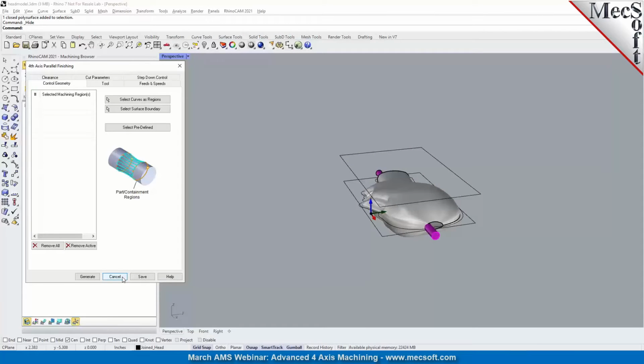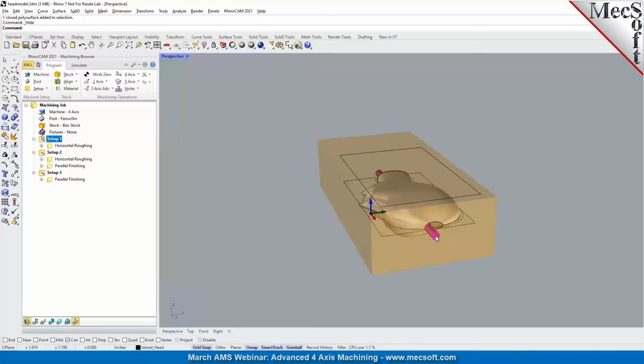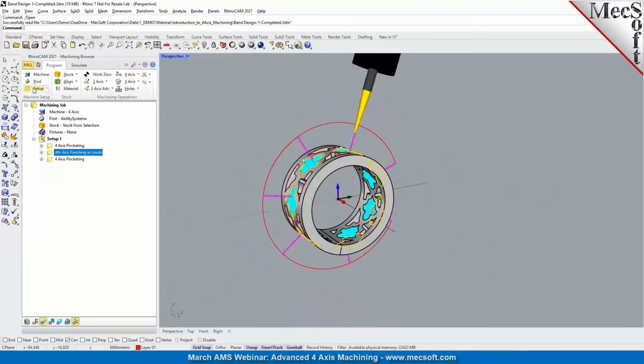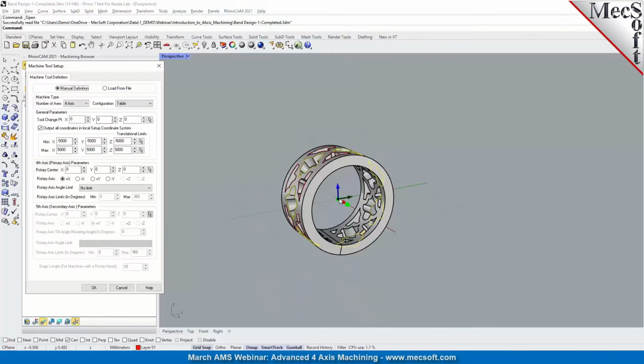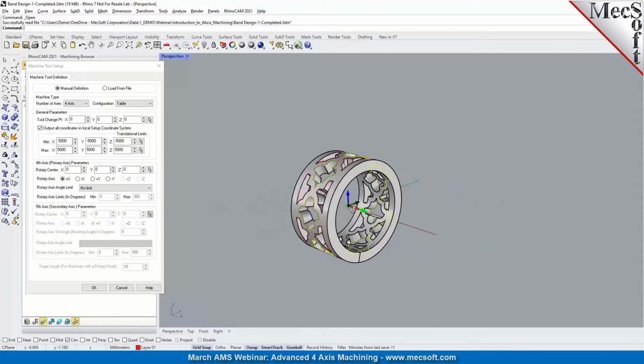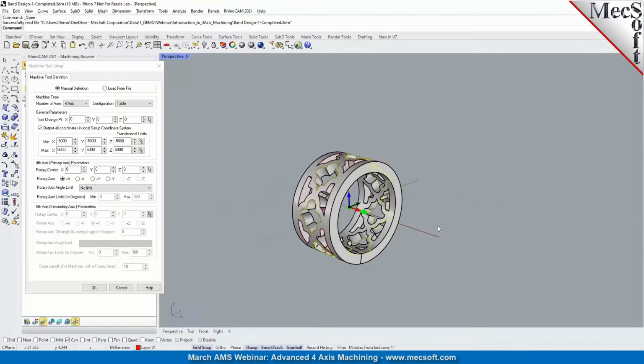If the machine is not, then you need to make sure that your XYZ origin and the rotation center are right on top of one another. So in this particular example, if I go back into this particular file, you can see that the rotation center and the XYZ origin are coincident, or basically, at the exact same location. So if the machine can handle the offset, then you can set the origin and the rotation center with the offset locations.